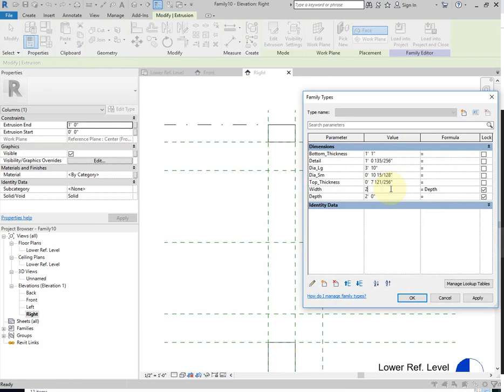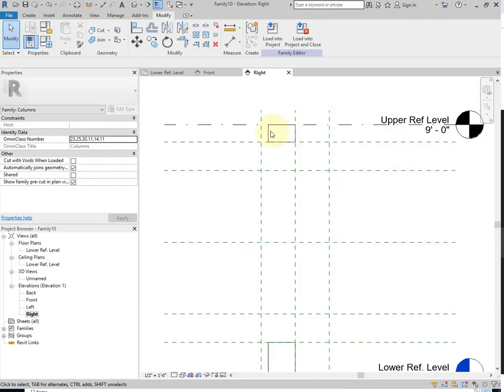I'm going to make it 2.5 feet. And I see the front's not connected either, so I'm going to align my reference plane. That's the reference, the front, lock it, back reference line, back, lock it. So now it will stay connected to it as you adjust and flex the design.